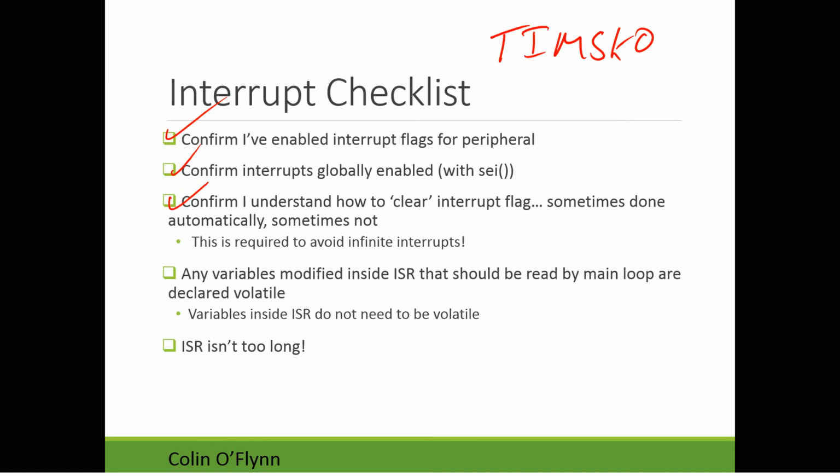If you don't clear the flag, the interrupt will also just run again. Even though the event only occurred once, the microcontroller thinks, hey, I should run this interrupt once more because this guy never dealt with it. So you need to clear that flag to say, yes, I have dealt with this interrupt. You don't need to call the code again.